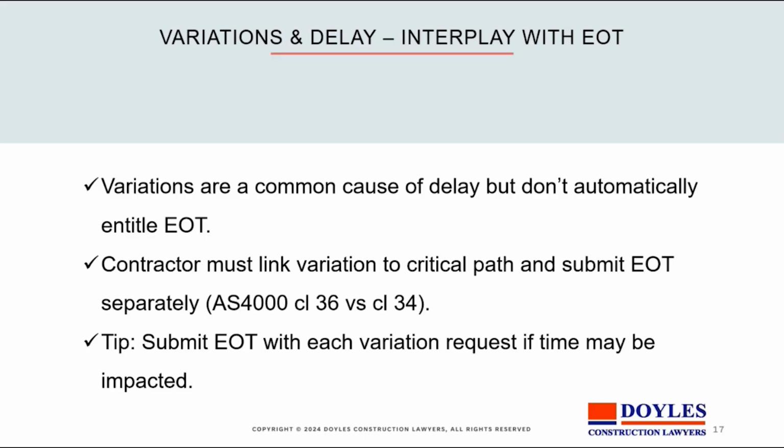The other aspect is it's proper when you do a variation to watch whether there is an EOT. So the situation is for every variation, one should look to see whether there's a resultant EOT. Oftentimes you find that while it wouldn't appear on the surface, a closer examination means that there will be at least some time reorganising supply chains, reorganising subcontractors, and reorganising a schedule of works in that area.